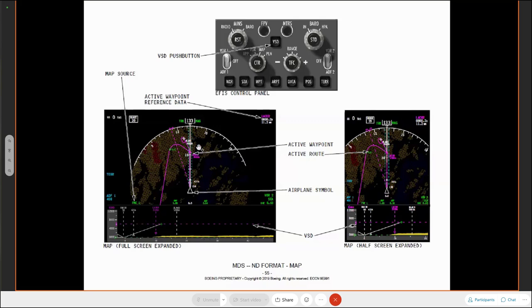Okay, so in fact, looking at this, I know that I am not flying the aircraft either by flight director or autopilot using LNAV and VNAV. Okay, so I'm probably flying it manually, or I'm flying heading or something of that nature. If I had LNAV and VNAV selected as an autopilot or flight director mode, then these cyan dashed lines would not necessarily go straight out.